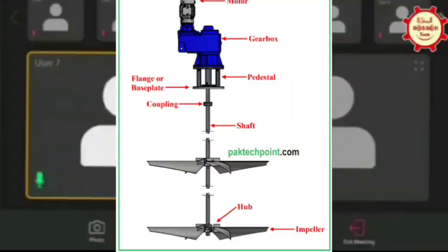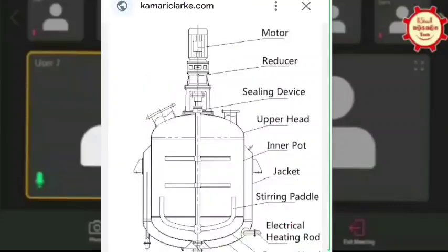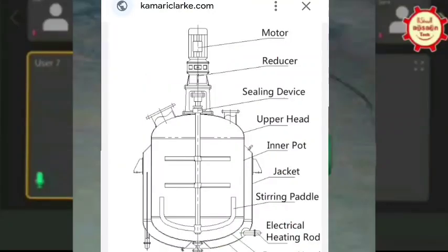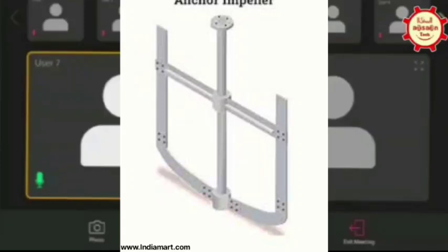There are two things here. One is that your shaft is coming till 11 mm, the gap between the bottom dish. Another is the blades. So how much gap is there between the blades and the bottom dish? The blade and bottom dish distance is 11 mm. The blades go completely till the end of the shaft, at the bottom. It's an anchor type.